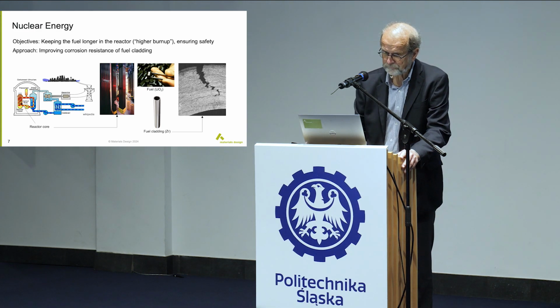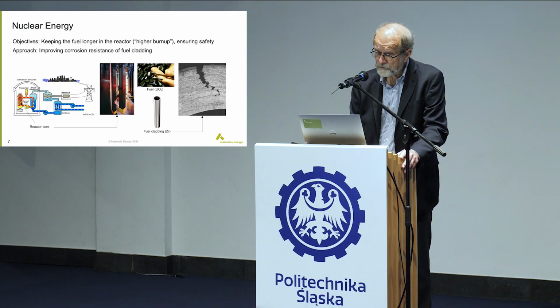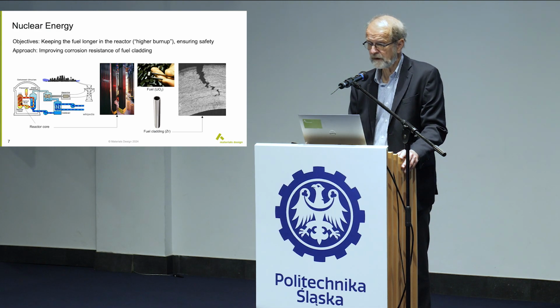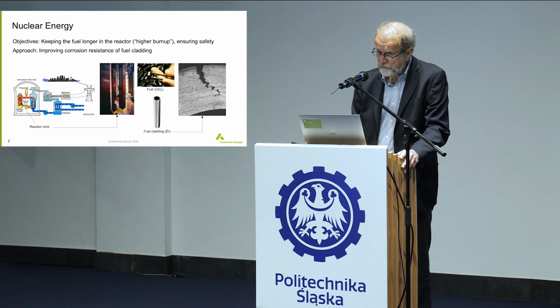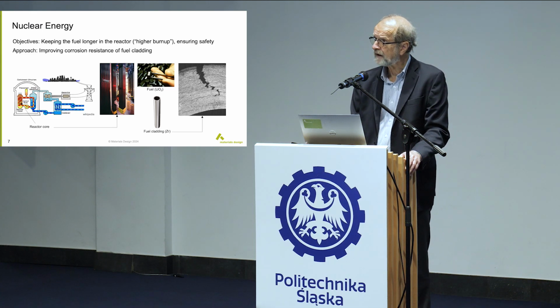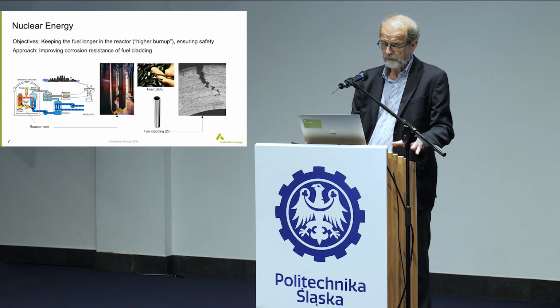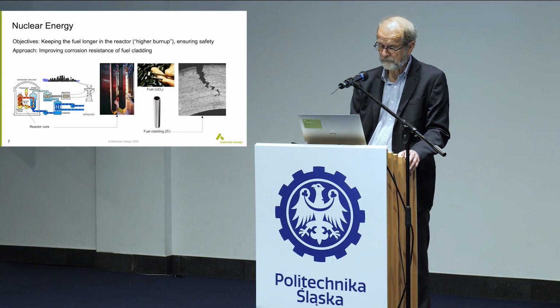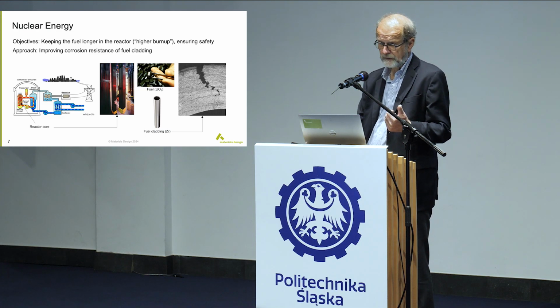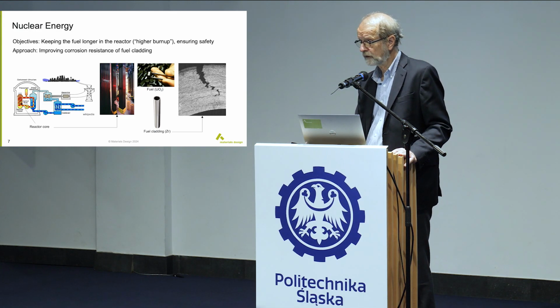So this core consists of these fuel bundles, and in the fuel bundles you have these cladding tubes. They are zirconium alloy, almost pure zirconium actually. And the fuel itself, you see here, is uranium dioxide. They're these little pellets, stacked in these tubes. They're about 4 meters long. And you see here this gentleman assembling these tubes. And then you put it into this relatively harsh environment. You have high radiation, because high neutron flux damages the material. You have heat, and you have a corrosive environment, water.